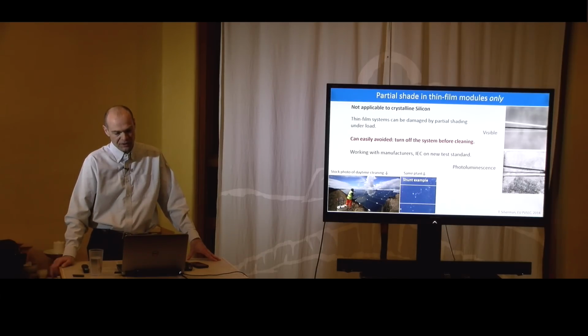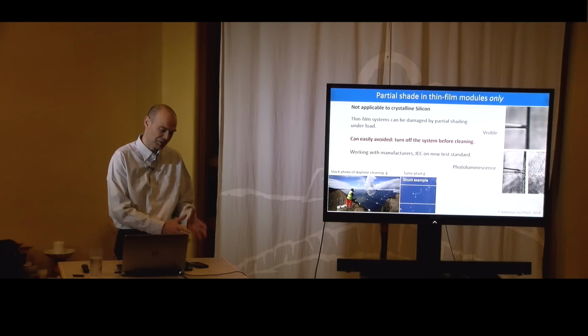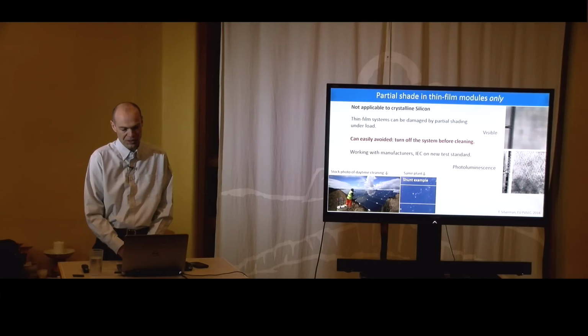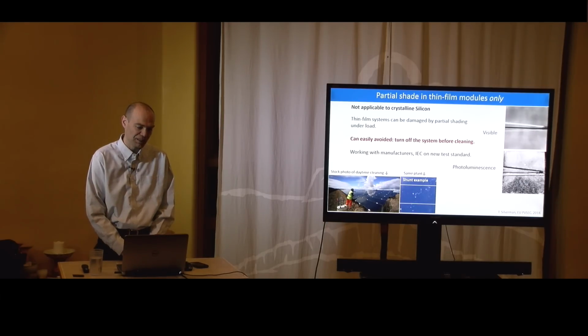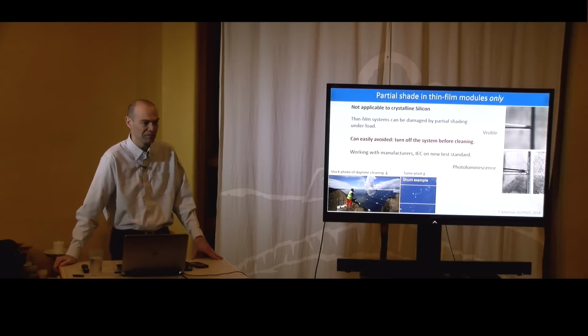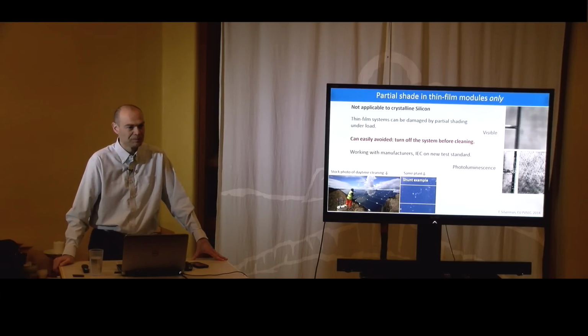And what exactly fails? Typically, what fails in an inverter are the power transistors and capacitors. There are new trends coming on replacing the power transistors with wideband semiconductors. They're better in switching and can sustain higher temperature, so that probably has an impact on inverter reliability. But we're just getting to the point where this comes onto the market.